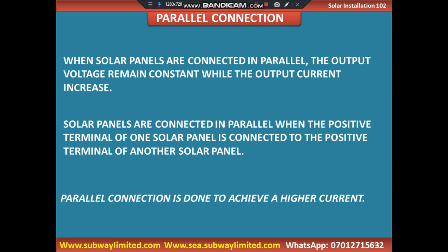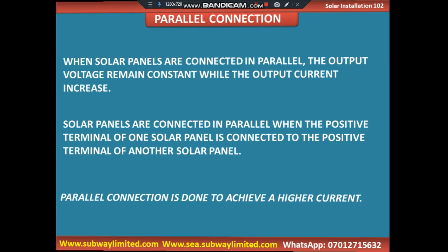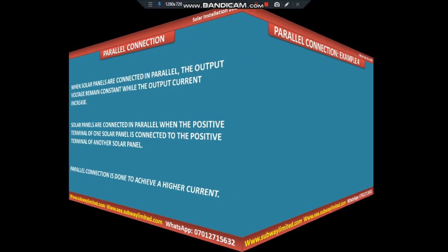And we are saying that parallel connection is done to achieve a higher current. If you need a higher current to charge maybe your battery, or as the case may be, depending on the specifications of the component on site, you should know how to connect your solar panels.